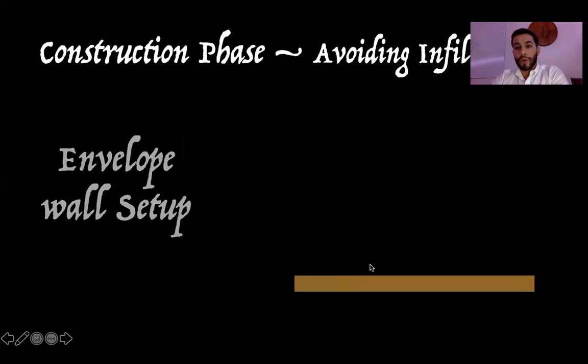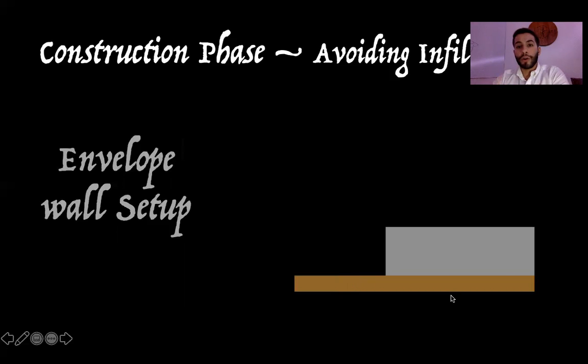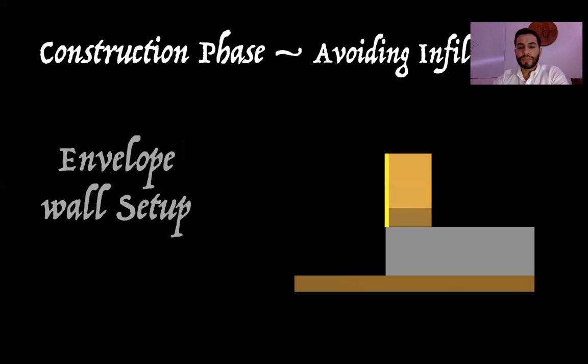So here you have your ground, you have your concrete foundation, you have your base, and then you have your 2x6 stud as your framing, your wall essentially. Then we like to use 1/2-inch OSB sheeting. This is a little bit thicker than your standard size, but again, improves efficiency. And something we like to do is mount our wall directly flush with our foundation, because this ends up creating a tighter seal.